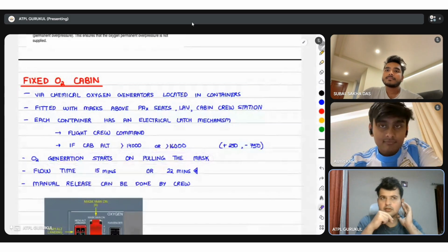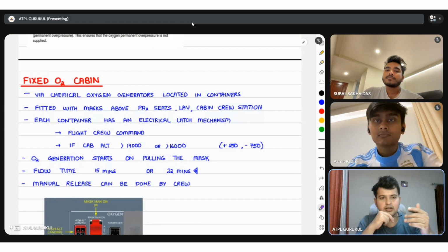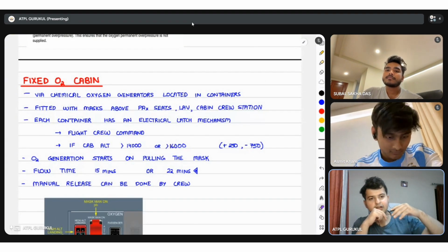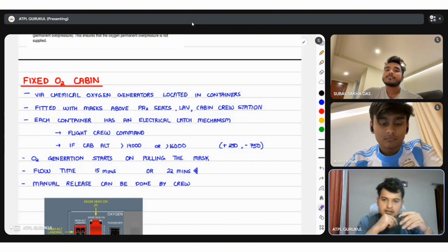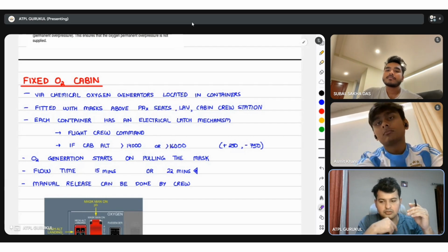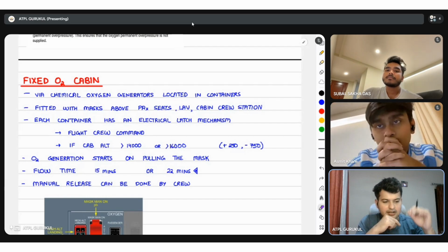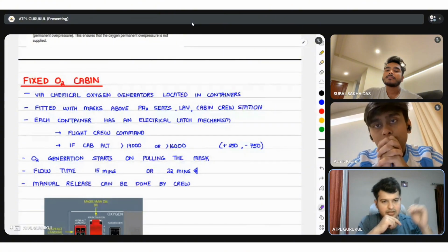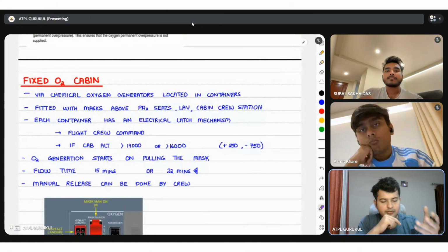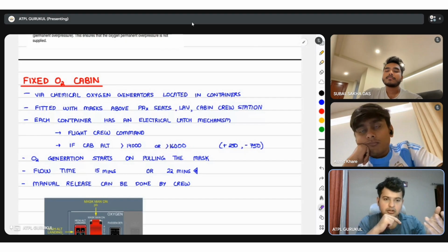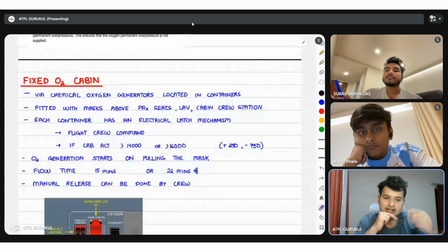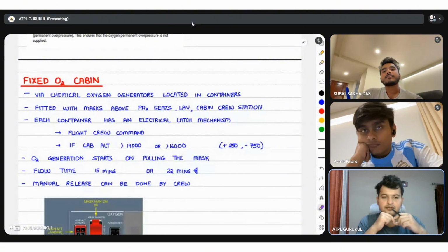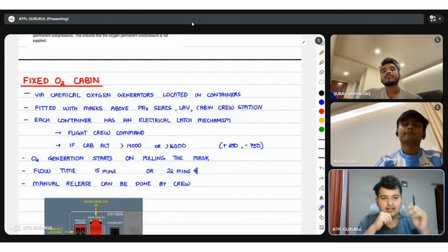Now when you're operating on critical terrain routes, for example when you're flying over Afghanistan, over Muscat, or over Leh Ladakh or through the Himalayas, you basically have to make sure that wherever depressurization happens, we can come down to a safe altitude. We have to come down to 10,000 feet or the minimum safe altitude, whichever is higher. What if you cannot come down to 10,000 feet? Then you have to plan for an escape route. And you can only send a very few specific aircraft on those escape routes.